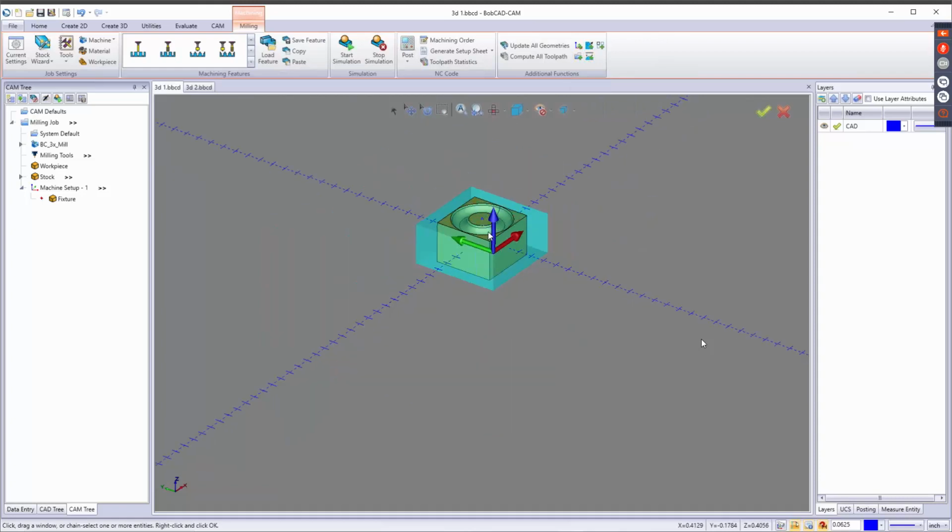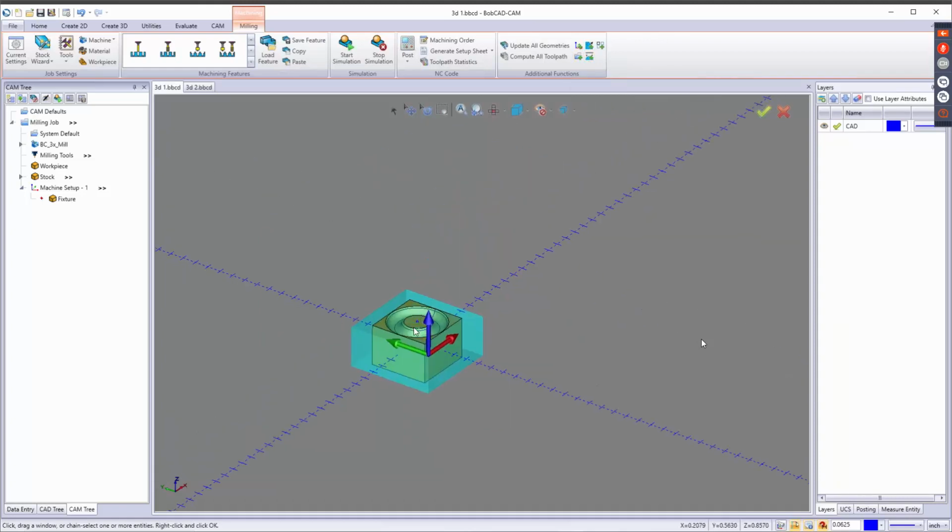Add a toolpath pattern to say if I want to do another one of these over a certain distance in X or Y, and I can put as many in there as I want. So basically you drew it up one time, you toolpathed it one time, and now you're just going to put in these toolpath patterns. It'll do one, then the other. Actually, it'll do it by tool. So whatever tool we use first, it'll do that for all of them, and then so on.